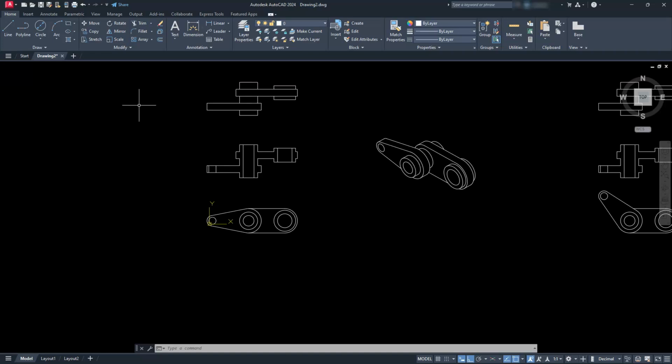The benefit of not doing this is that, yes, you can have multiple pages, but they're going to all be different sheets, right? But the sheets will be a lot smaller. This file will get longer and bigger and bigger as you create more sheets in paper space. Whereas if you did it separately as a drawing, the file size will stay relatively small, depending on how complex your drawing is. All right, let's just go ahead and switch over to layout 1.